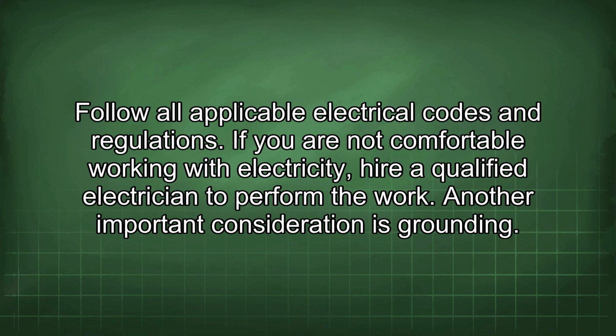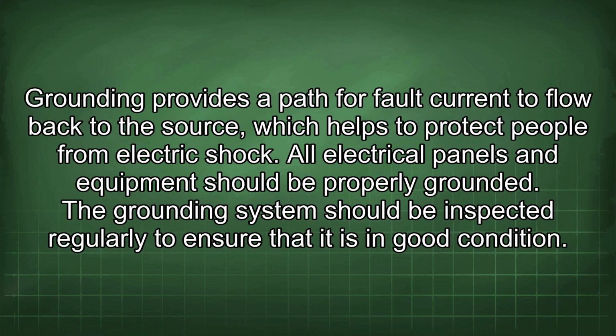Another important consideration is grounding. Grounding provides a path for fault current to flow back to the source, which helps to protect people from electric shock. All electrical panels and equipment should be properly grounded. The grounding system should be inspected regularly to ensure that it is in good condition.